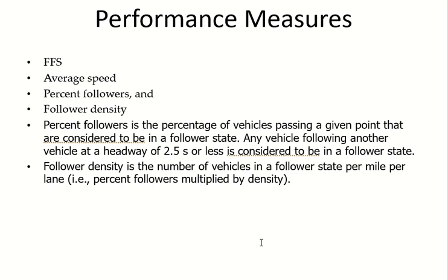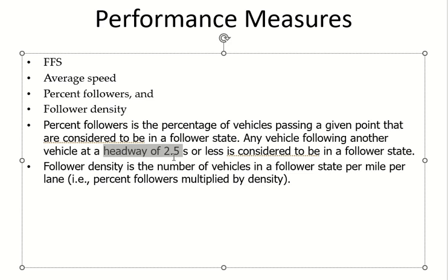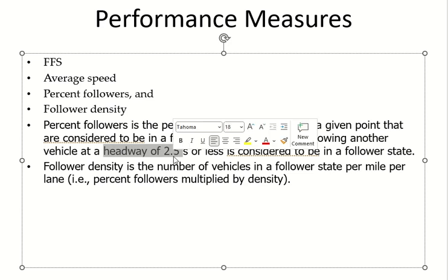So what is the threshold or limit for that? 2.5 seconds of headway. So any two drivers driving at an interval of 2.5 seconds or less are considered followers. Okay. So out of 100, how many are having headway of 2.5 seconds or less? They are percent followers.